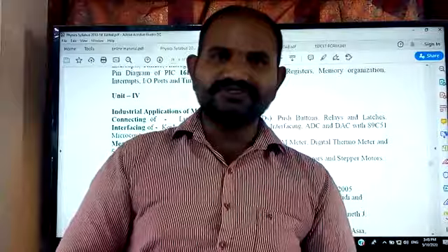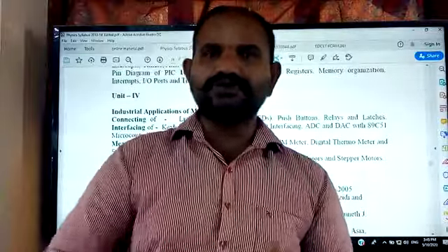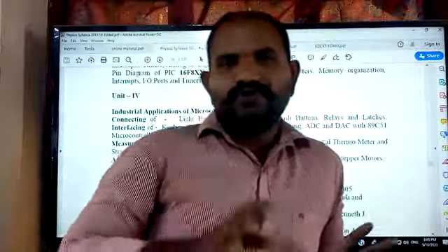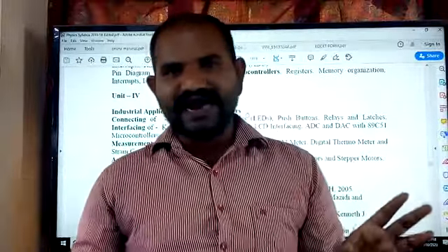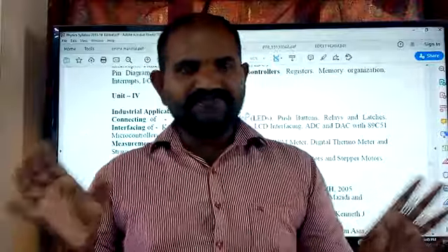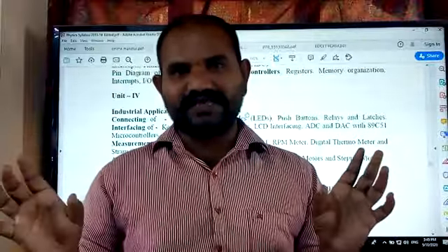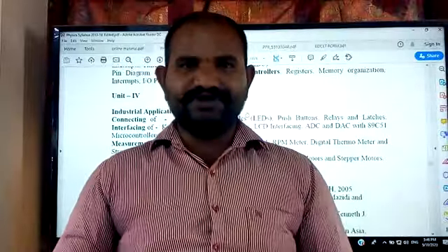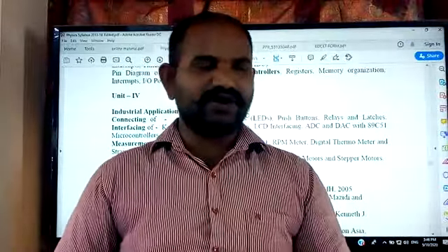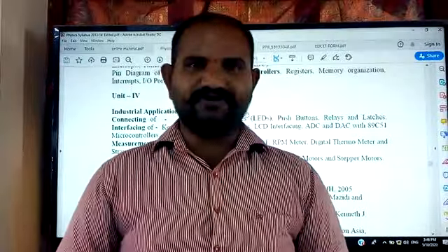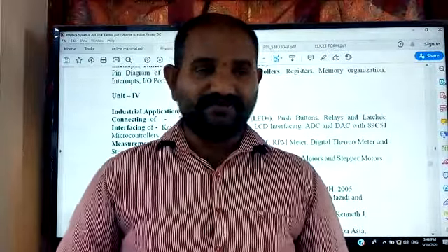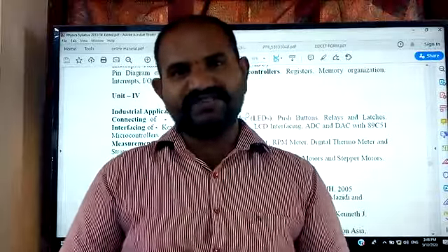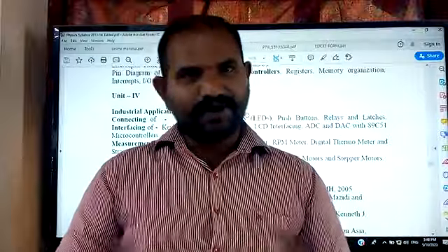Amplifier is nothing but buffers. So the buffers are going to amplify the information, and that information is going to be transferred to the IC properly. When you would like to interface one IC with another IC, there is a power requirement. If these power characteristics are not satisfying the IC's expectation, then even though you are sending the information in terms of voltage, assuming 5 volts as binary 1 and 0 volts as binary 0, you will ask why you are not getting the outputs and why the IC is not responding. It is because of these power characteristics.